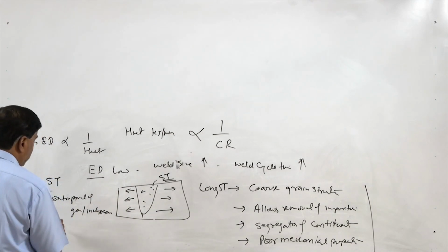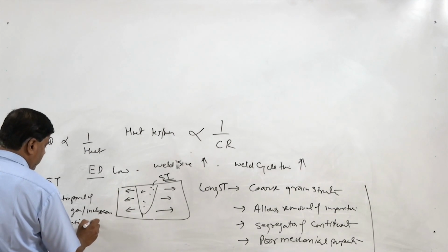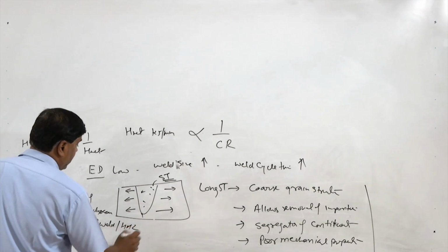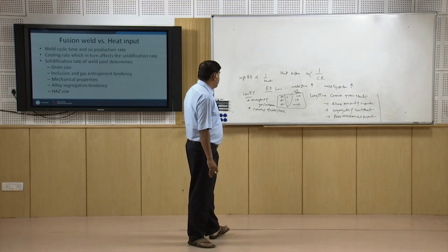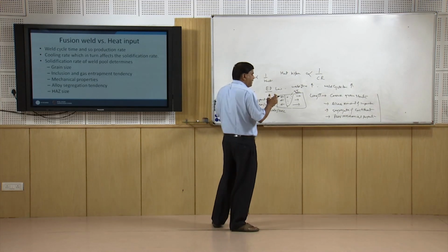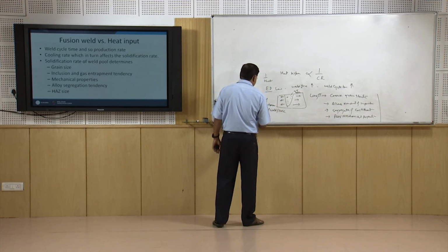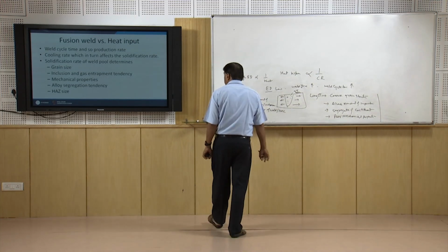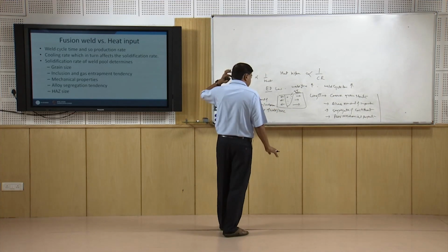This is one thing, and it can lead to the cracking of weld and HAZ, especially in the case of steels or the hardenable steels. So sometimes preheating is done intentionally, so that the cooling rate can be reduced and the solidification time can be increased. So these are the different aspects related with the